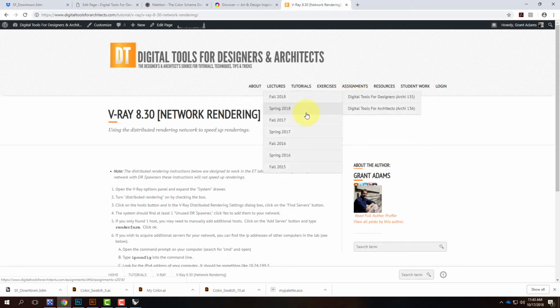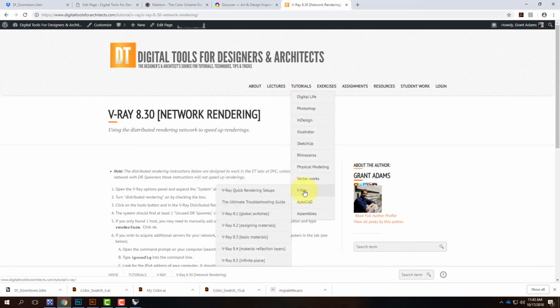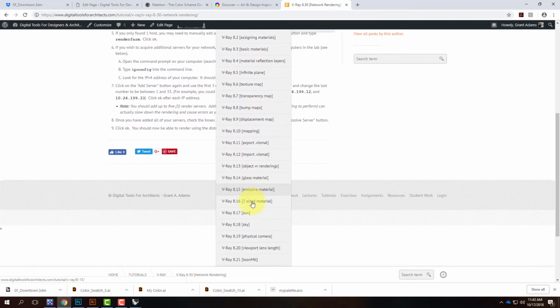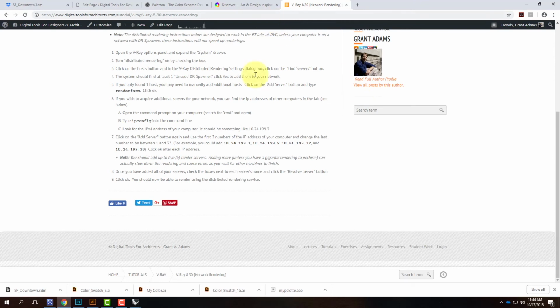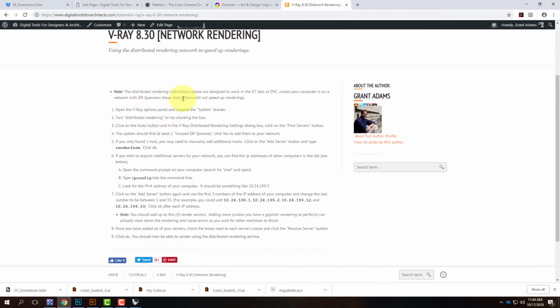It's just here. By the way, everything else that I did cover is under V-Ray, and I have links to them right here: 8.17 for the sun, 8.18 for the sky, and 8.19 for the physical camera. Those three are what I just did. So if you want to go through any one of those, or if I went too fast, you can go back and review those there. And 8.30 is the distributed network rendering. This is specific to the ET lab. So if you have V-Ray at home and you try to do network rendering, it's not going to help you. So it is specific to being here on the lab computers.